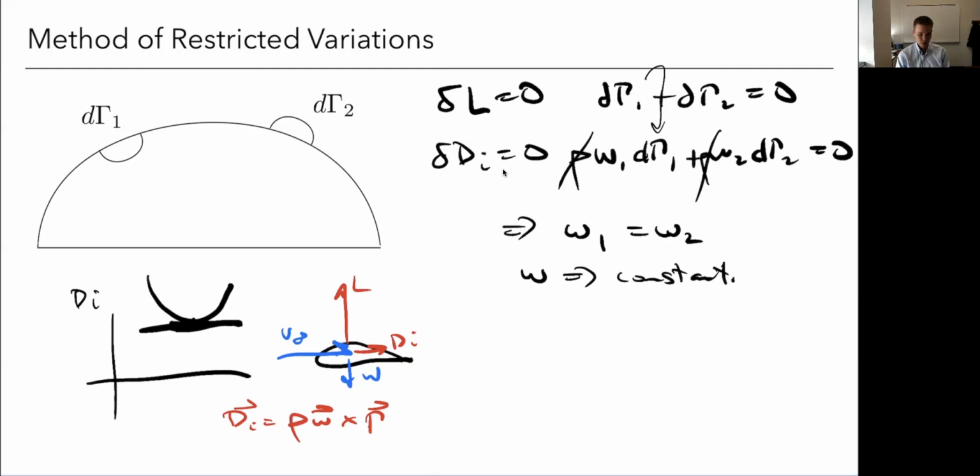Well, remember Kutta-Joukowski is rho V cross Γ, right? That the force that's produced is rho V cross Γ. So we have the direction of V, here's V, but what's the direction of Γ? Well, again, let's think about the top view. Here's a top view of a wing, right? And if we drew like a little horseshoe vortex, recall the direction, Γ looks like this, right?